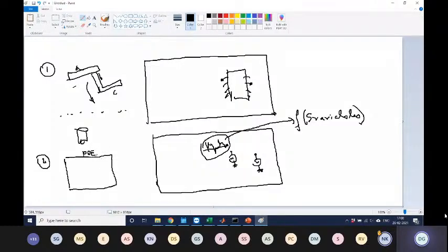That's a very favorite topic of mine, because I think that's one of the ways we can actually make it work. The challenge in the electromagnetic domain is the close coupling between every object and every other object, right? Everything interacting with everything makes it a sort of multi-agent problem, with every node connected to every other node, which makes it hard. Typically these solvers use Krylov subspace-based iterative techniques, where you go down in terms of your error, like a typical iterative solver procedure. What we were able to do is learn from structures that have been solved before and harvest that Krylov subspace and use it to converge faster.